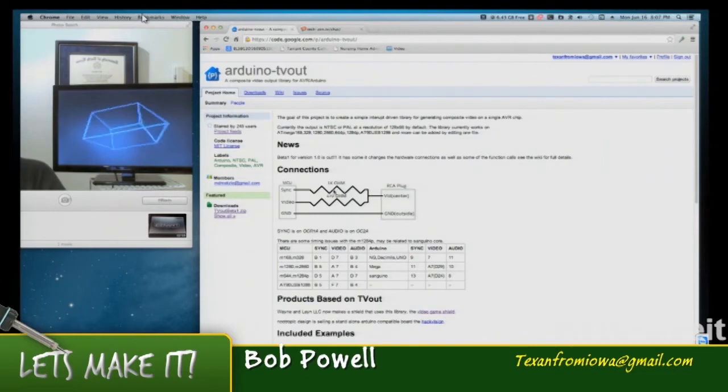And in the end, I think a lot of it may come down to this 1K ohm and 470 ohm resistor right here. The way I've looked at it is that if you take 1,000 and divide it by 470, and forgive me for the math, you get 2.1276. And I finally found a combination of resistors that would give me 2.1299. And that's what we're looking at right here.